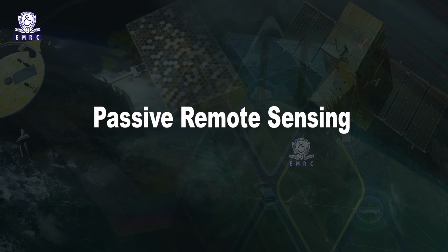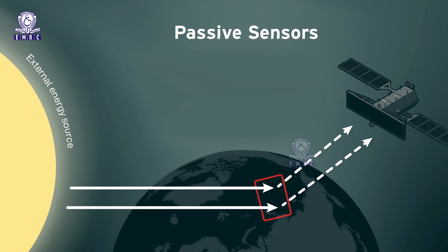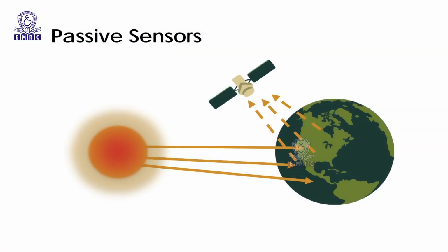Passive remote sensing. Passive sensors measure light reflected or emitted naturally from the surface and the objects. Such instruments merely observe and depend primarily on solar energy as the ultimate radiation source, illuminating surface and objects. Therefore, except for the thermal sensor, they cannot be used at night time. Thus, in passive sensing, there is no control over the source of the electromagnetic radiation.